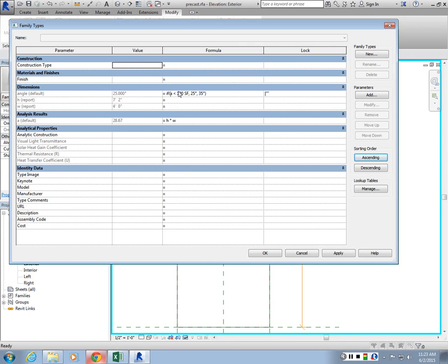So technically what I want to set is, if area is less than 100, that means it's a smaller panel, so my angles could be larger. Under the true statement, I could write another nested if statement: if area is greater than 50, use, let's say, 35, else use 45. And for the false part, which is a large panel, I want smaller values. So if area is greater than 150, I want to use 10 degrees, else 15 degrees.